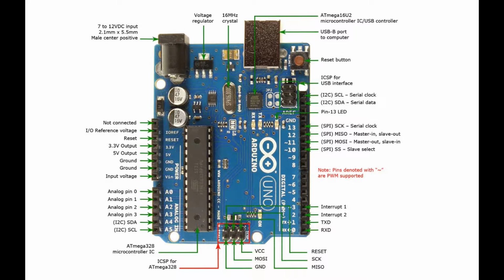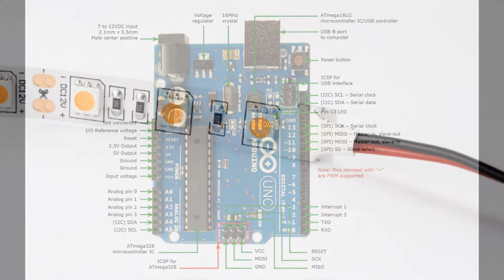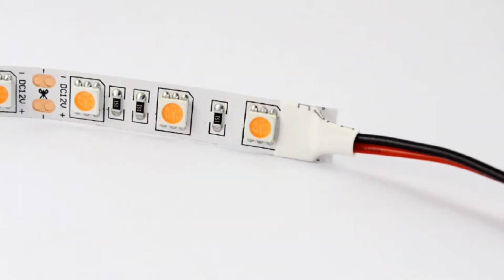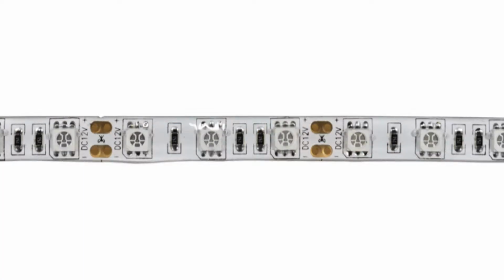The available power varies according to the power supply used. A maximum of 500 milliamps is allowed with the USB port. For example, an LED model 5050 consumes 240 milliamps alone. We will see how to resolve this issue later. Some LED strips have only two connectors, the voltage in and the ground, which limits their state to a single color that is predefined by the manufacturer.